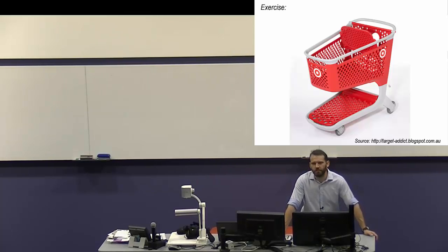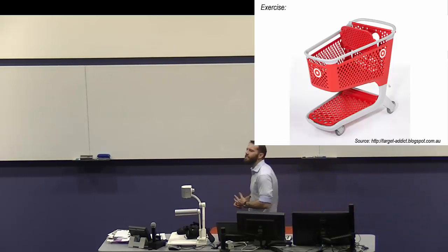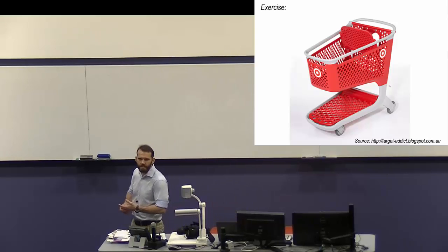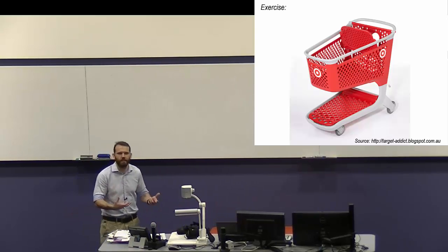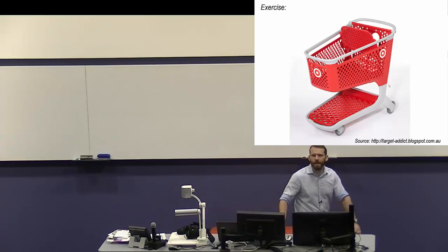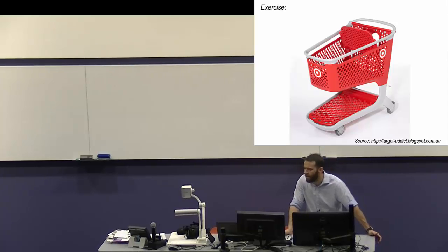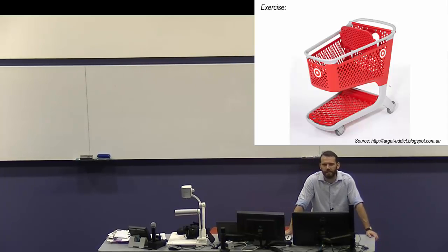What's a negative with the actual material? Plastic can go brittle, yeah? Plastic can melt in the sun, yeah, so you'd have to be very careful about what sort of plastic you used. Colour would fade, yeah, so plastic has a really bad UV resilience. You can get UV resistant plastics, but still the plastic fades. Think of your pegs on your clothesline if you've got plastic pegs. They've got UV stabiliser in them, and all of them end up a really light shade of garbage by the time they're old. So UV stabilised plastic is critical, and it can still probably degrade. Anything else?